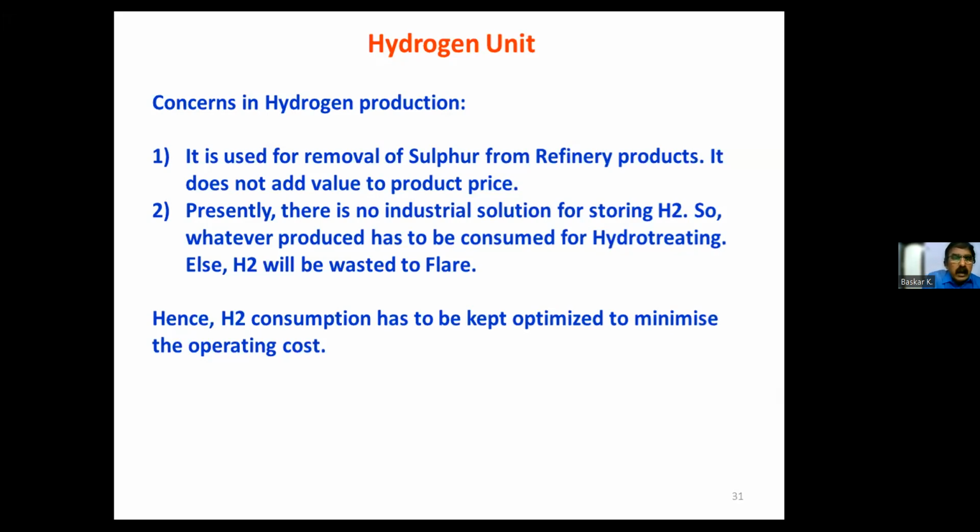And there is no industrial solution presently for storing hydrogen. A lot of hydrogen is required for these operations, and we don't have any industrial solution for storing hydrogen. So whatever hydrogen is produced has to be consumed for hydrotreating. Else, hydrogen will be wasted to flare. So hydrogen consumption has to be kept optimized to minimize operation cost.